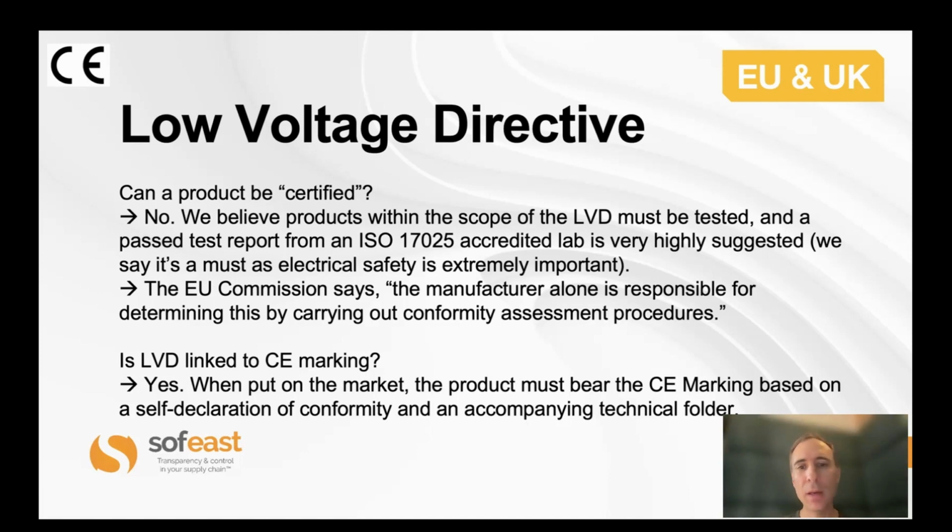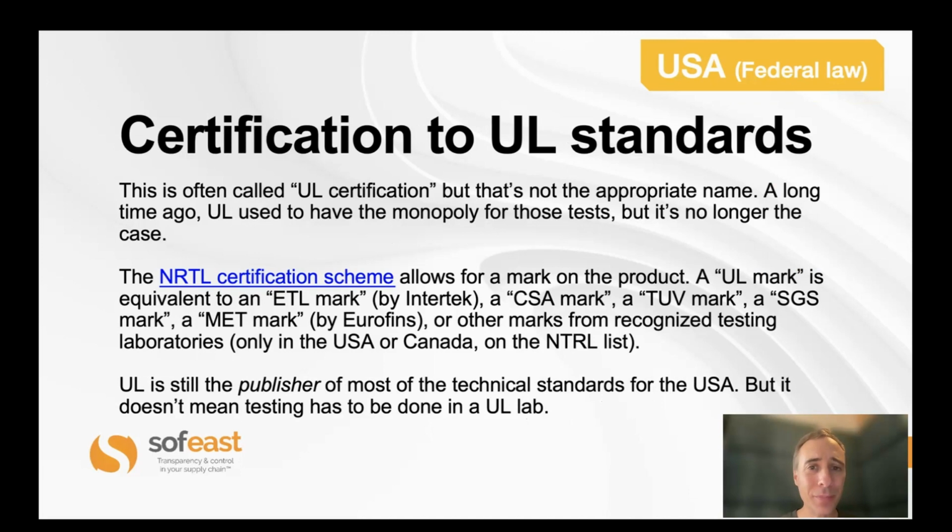But in this case, the general logic of CE marking, for what they consider not very high risk products, is that the manufacturer is responsible. If you are the importer and you put the product on the market with your brand, you are considered the manufacturer. The manufacturer is responsible for doing proper risk assessment and taking the right measures. And yes, LVD is linked to CE marking, and it comes with a declaration of conformity and a whole technical file, not just the CE marking on the product.